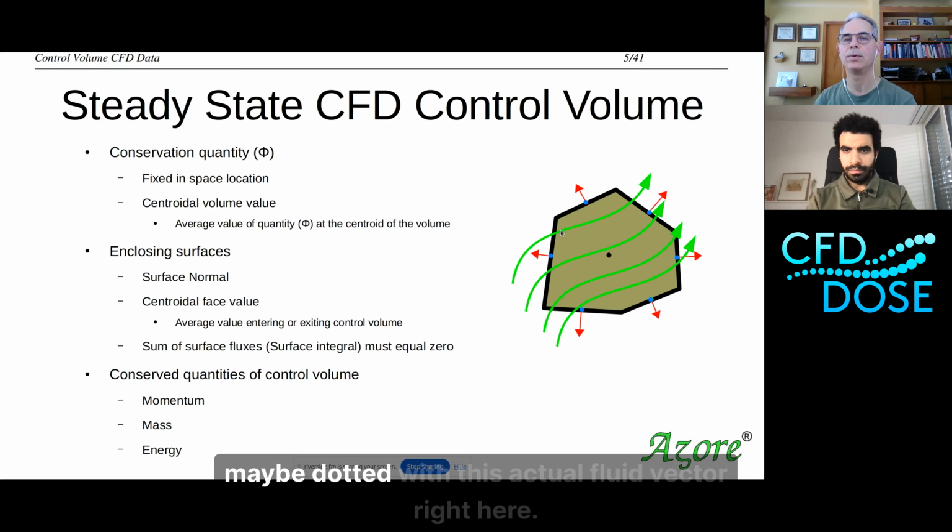And here I'm just going to look at the conservation of mass, for instance. So we have a box here. It's a volume, and we have some mass flowing in on one side of the box and leaving on the other. There are some inherent things that we know just based on conservation of mass. For instance, if the mass coming in and out is constant, then the mass inside the volume is constant. But if the mass going in and out is not constant, then either the volume, your control volume, has to change, or the mass inside the box needs to change.